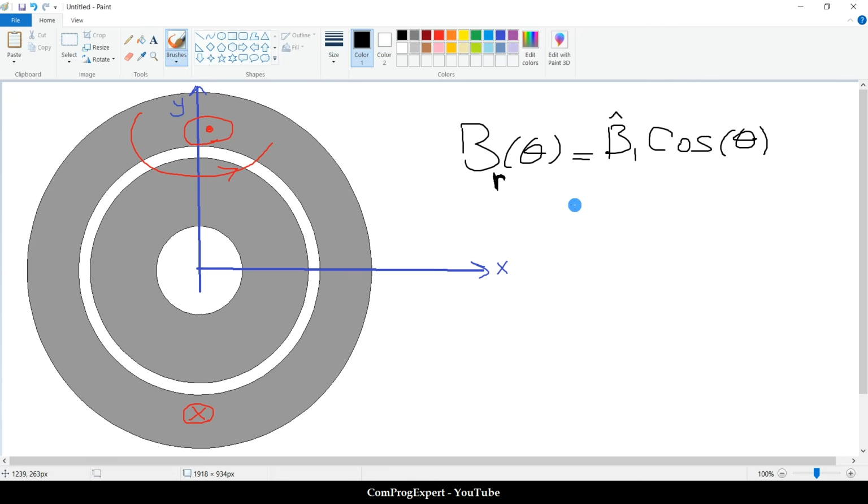Yes, the vector field. When you have a vector field in MATLAB and you want to plot it, a vector field like this, F, you should specify the x, y coordinates of the point and the Fx and Fy components of the field vector that is attached to this point. So in this case, if we consider this point, this is the BR. If we only consider the BR and neglect the tangential component, but in a real case, we cannot neglect the tangential component.